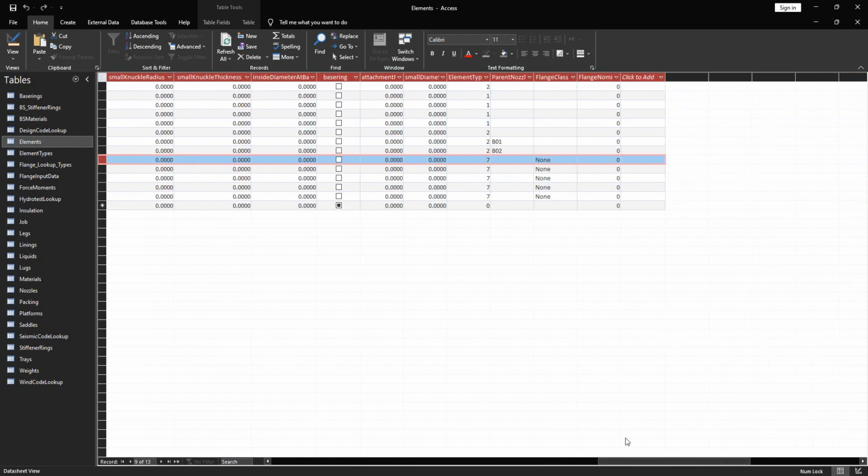So if we come back here, you will find that no nozzle is mentioned for this blind flange, and that's one of the mistakes in the Access database file which was exported from BVL. So no information here regarding the type of this flange or for which element it will be connected.